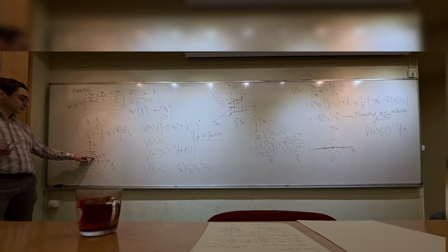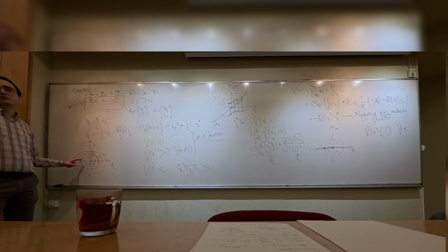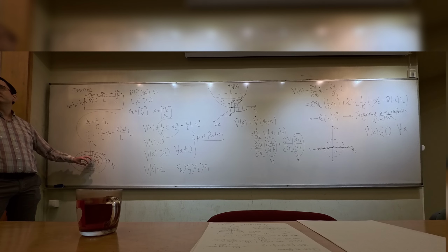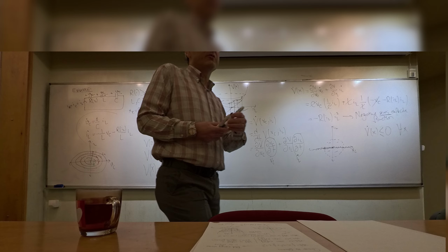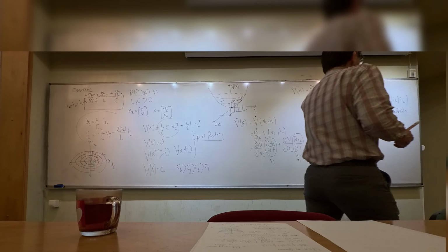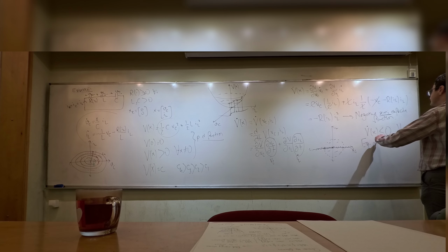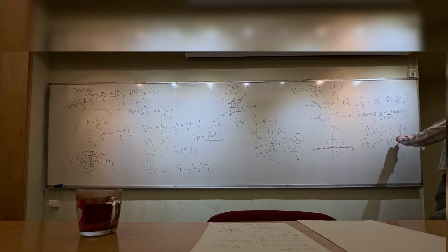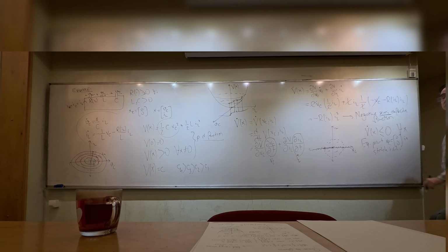Because V dot cannot be positive, I could actually conclude that for any such epsilon ball, we will be able to find a delta ball that would be satisfying the stability condition. So the conclusion from this type of analysis is that the equilibrium point xe equal to 0 is stable in the sense of Lyapunov. We could conclude stability based on the sign of V dot using this auxiliary function.